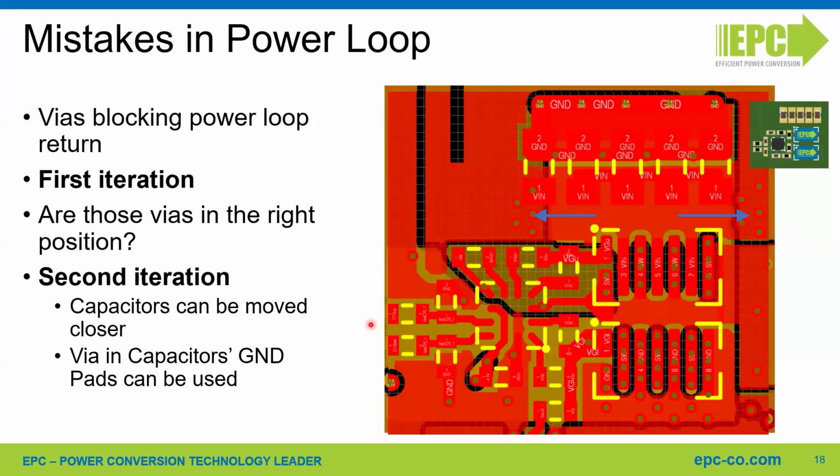So this is why we recommend, and we have only gate drivers recommended which are not supporting negative voltage drive. But of course, you can arrange a solution with a standard gate driver providing a small negative offset, but it's not really recommended. It's not needed. So the best solution is to not have the problem to solve. In this case, we are fine with 0 volt turn off.